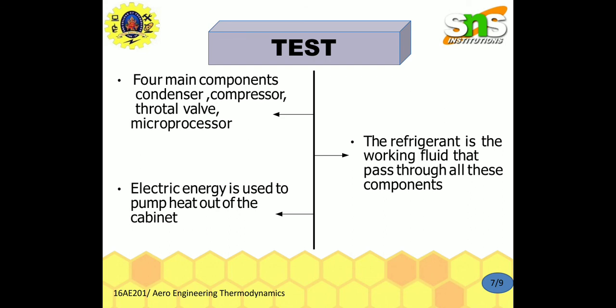The equation of COP is the relation between the heat transfer and the work done. U is the useful heat supplied or removed by the considered system. W is the work required by the considered system. The COP of a refrigerator is given as the desired output divided by the required input, or equivalently the cooling effect divided by the work input.